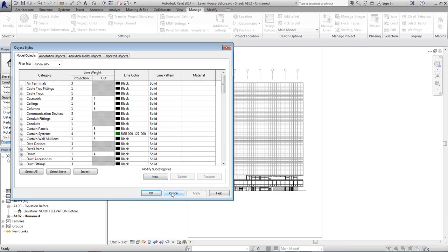The other thing is you just got to be careful. Sometimes you want to make sure that your lowest line weight is not the lowest that you can make it, so you want to give yourself a little space. Making all of your projection line weights 1 by default means you can't go any lower. So maybe it makes more sense to make the default projection line weight 2, so that someone could make it lighter, and there's still some space below the standard.